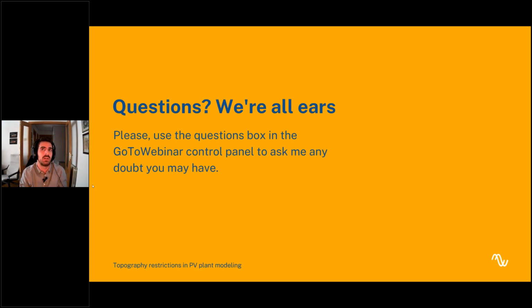Which means that I think you need to look at the terrain yourself and evaluate the quality on your own, if you are interested, right? The other solution, when you are doing a detailed topography analysis, is to find your own data which you are confident in, right? Something like what I said, USGS, IGN in Spain, or whatever.